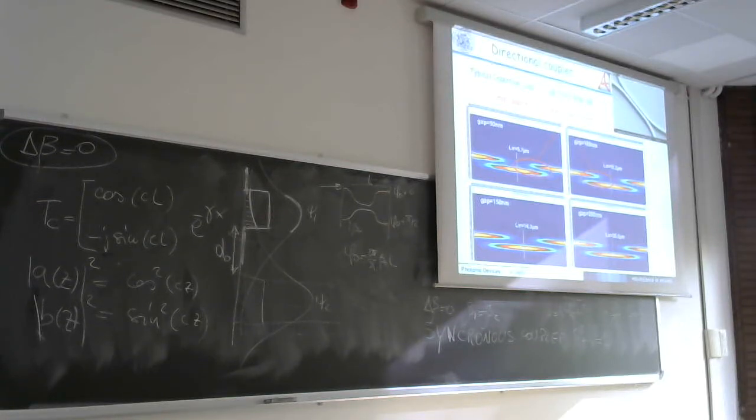There is an indication of cutoff when the excitation of the other mode appears as they become closer. You can put the two waveguides one attached to the other one, but there is no other guided mode that appears. The other modes that appear are leaky modes, radiative modes below the cutoff. The perturbation is so strong that you excite these modes, but the modes are not guided, so they go away.